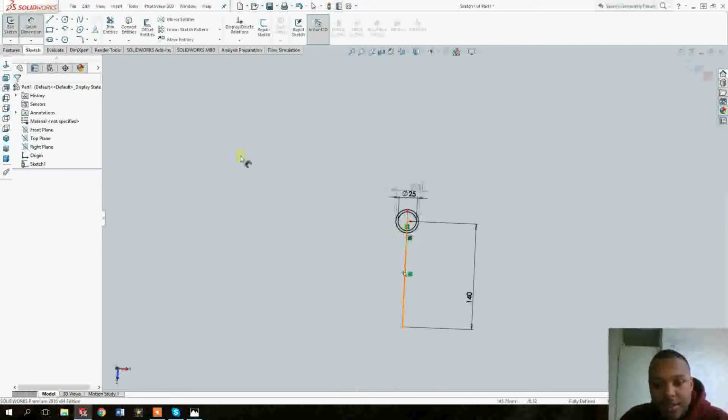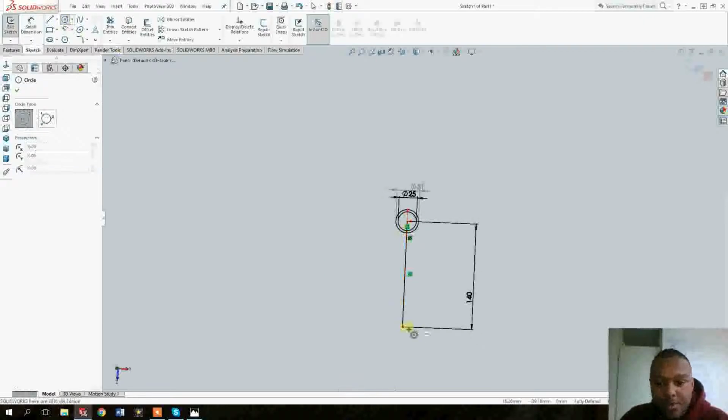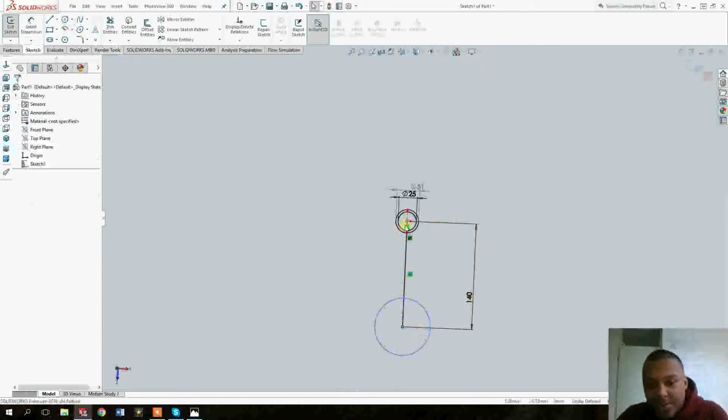That's also how you measure the connecting rod length, from the center of the bottom circle to the center of the top circle. So from the pin to the crankshaft. It's not from right here to the top of here or anything. It's from the center of this circle to the center of this circle.